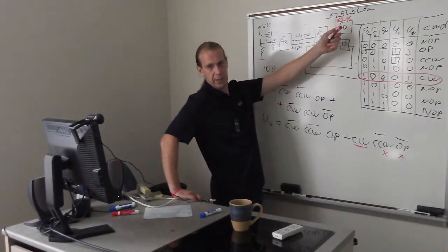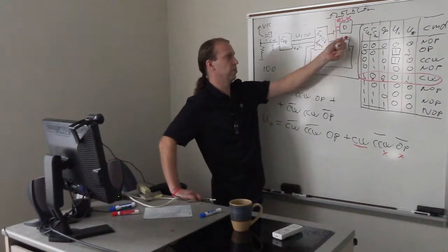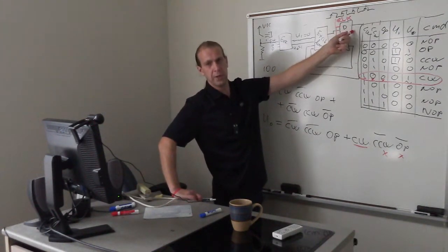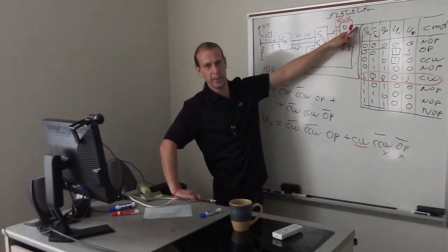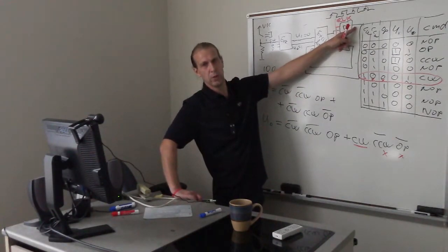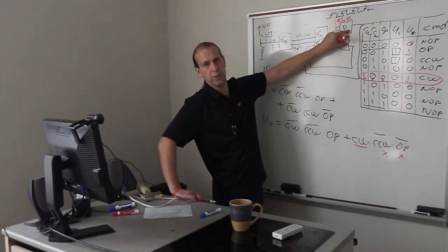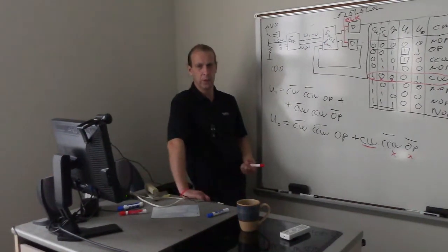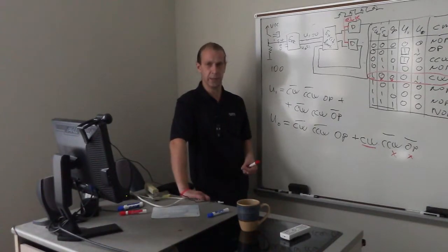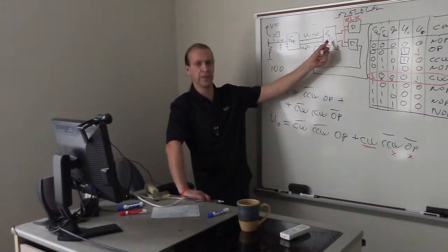The 4 states A, B, C, D are actually different combinations of these two triggers. So a trigger is a memory element. It has 1 bit of data. It can store 1 bit of data. Any output of the trigger can be in either of the states, 0 or 1. With 2 triggers, we have 2 bits of data to store. And 2 bits of data is enough to represent 4 states of our finite state machine. That's what we will be doing when we discuss the excitation function.